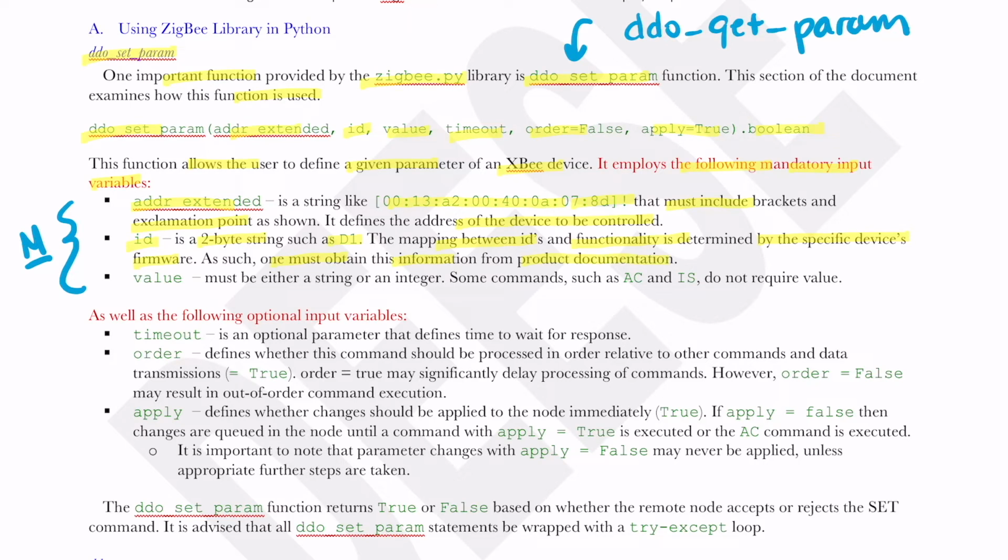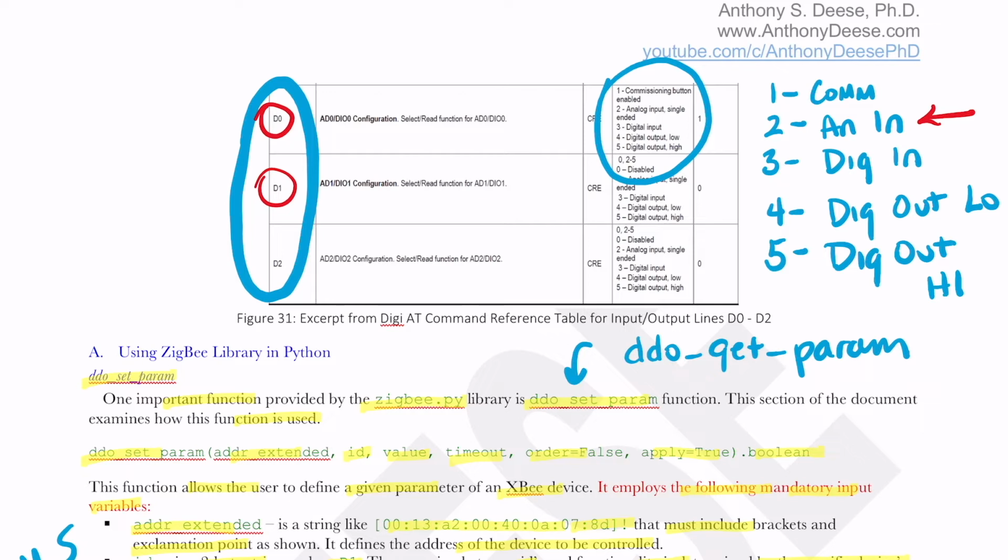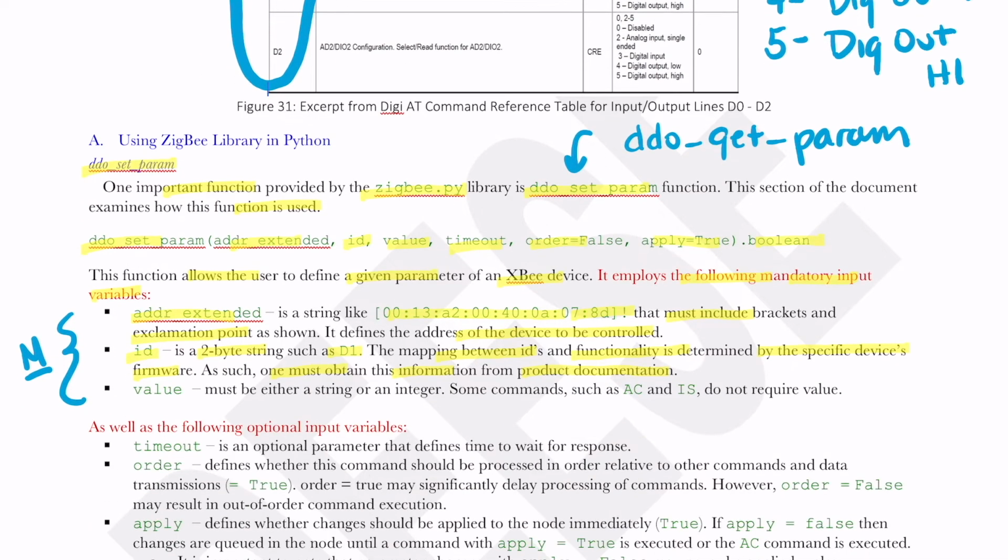Okay, and what we're going to be using for our base radio is going to be these AT commands. So some other devices may have additional commands on top of these. However, we, for right now, are just using the stock XBee radio Series 2, and so the values, the IDs, I should say, that we will have available to us will be those that were listed in that reference document. Okay, so we've dealt with that one.